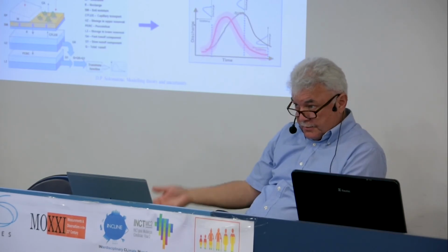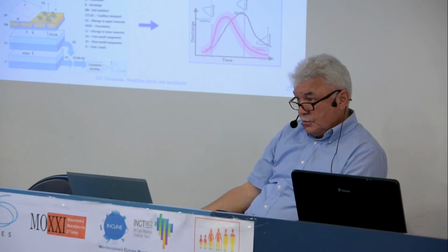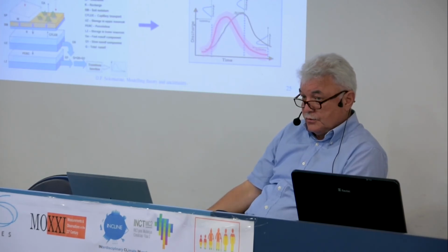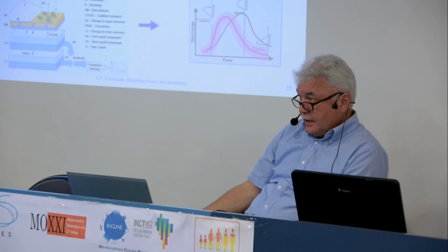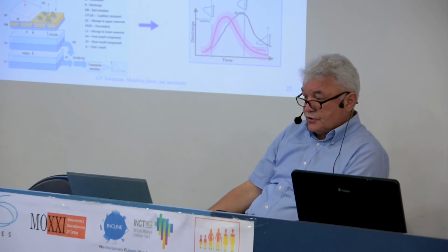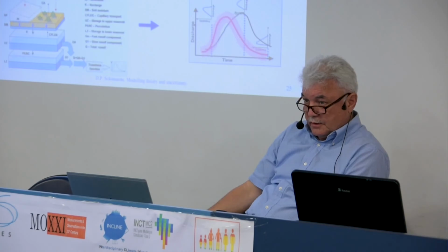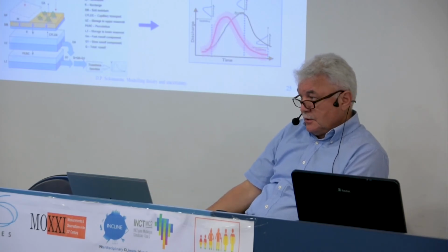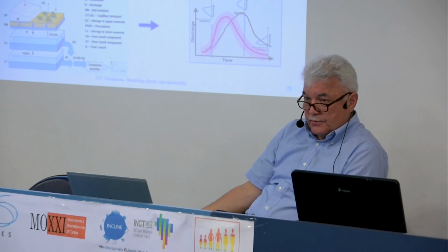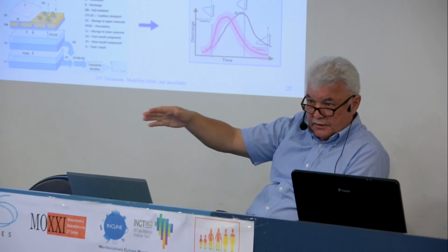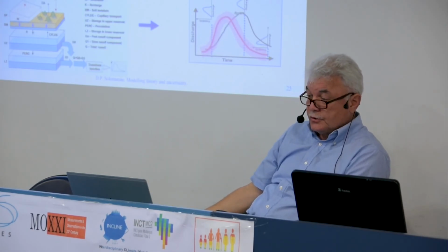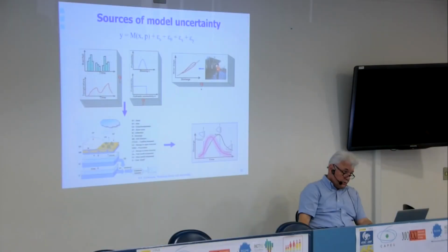However, some parameters you cannot measure, so you don't know what the error is, so you have to base it on your judgment. And I think experts would say, okay, we measured Manning coefficient or whatever we measure in rivers, other parameters or in catchments, and we could say, okay, there is a 30% interval, plus minus 30%, something like this. Good question. We don't know these distributions well. We have to assume something. I cannot say more than that.